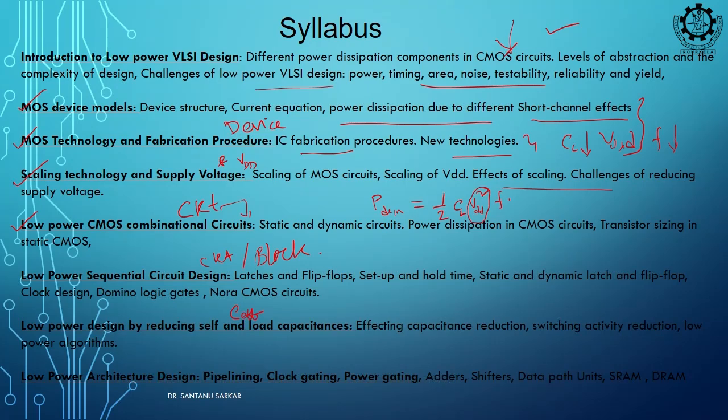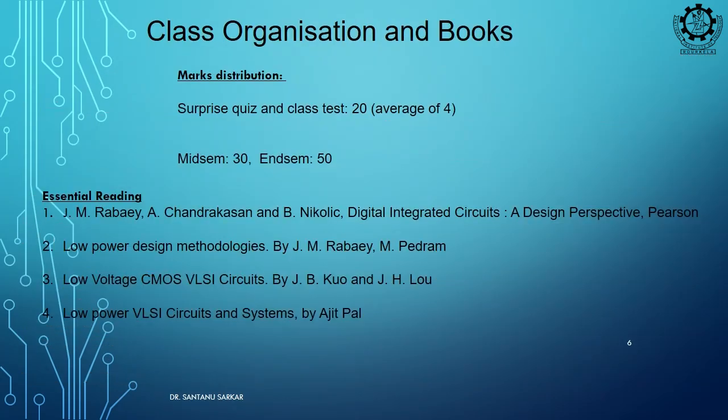After that we will be coming back to effective capacitance, C effective. In the equation, C is one important aspect. If you can reduce the effective capacitance, then we can reduce the power. There is another term, called alpha. Here this half will come as alpha. This alpha is nothing but switching activity. For example, suppose this is your clock, and at each clock you are flipping from 0 to 1 and 1 to 0, and in another case you are flipping after a very long time.